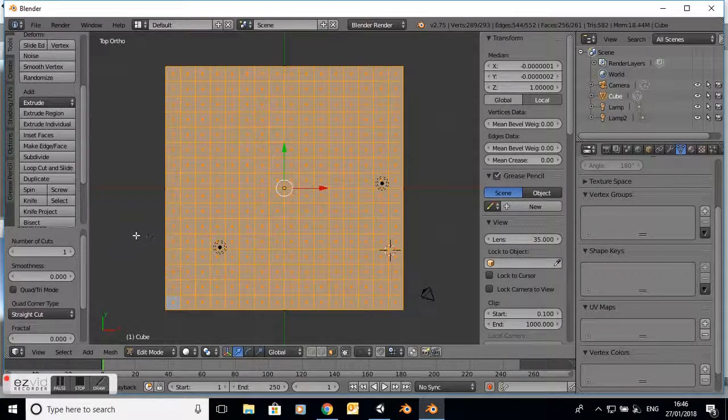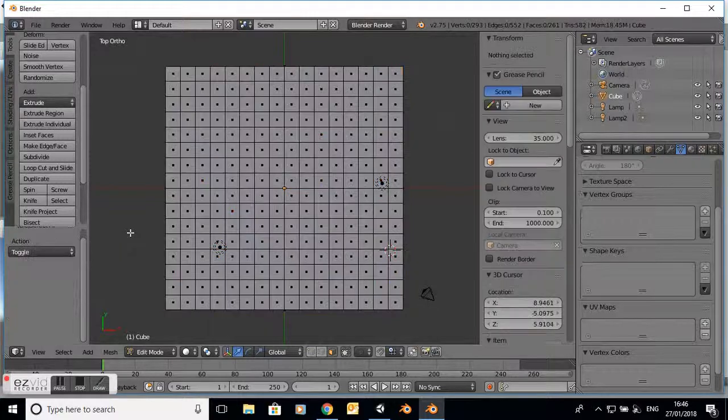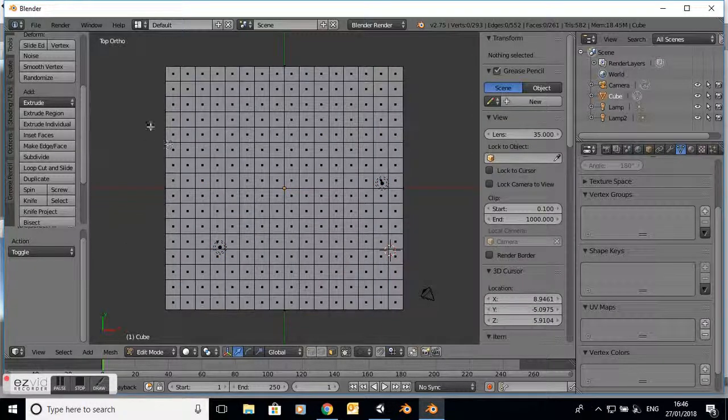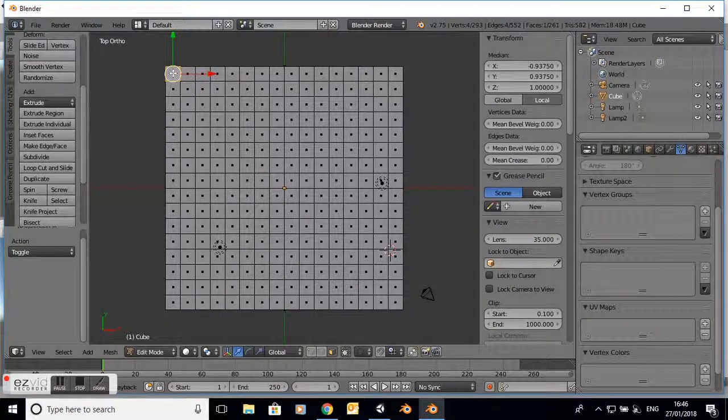Now you can select these squares by right clicking on the top surface, and then you can hold the shift key and click more. Okay, so you can multiple select that way. There is another way of multiple selecting which is a bit easier eventually, but a bit more difficult to set up. Another keyboard shortcut, C. So if I select C, this gives us multiple selection.